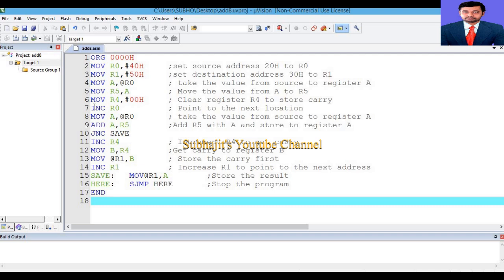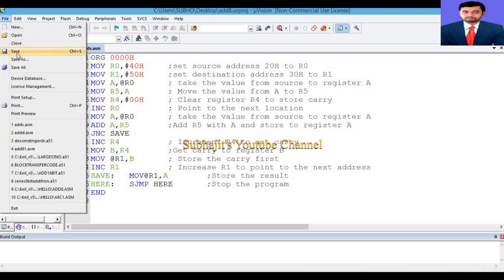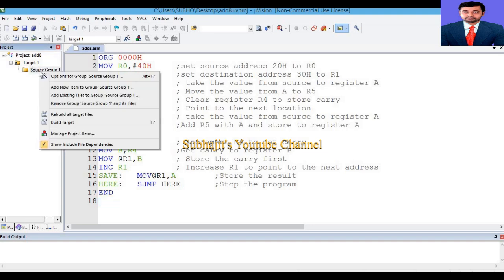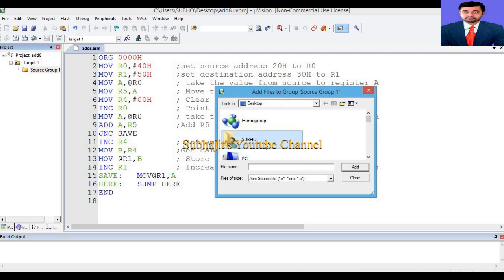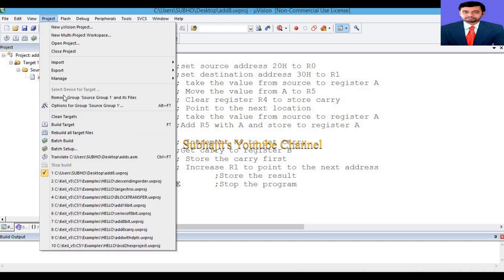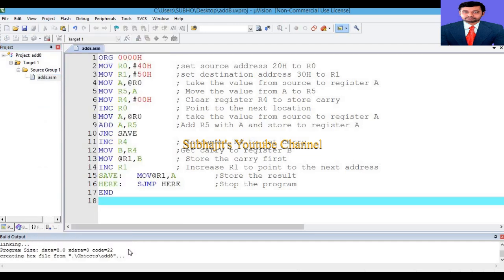Next go to file, save all. Next go to the source group, add existing files to source group 1, select the program, then add. Then you can see here under source group 1 this program has been added. Next go to project, build target.